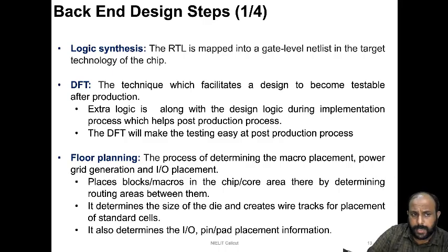So backend design steps, if you look at, the first step could be logic synthesis. In the process of logic synthesis, your verified RTL is converted to a structural equivalent, something called a gate level netlist. And this gate level netlist is very subjective to the target technology of the chip.